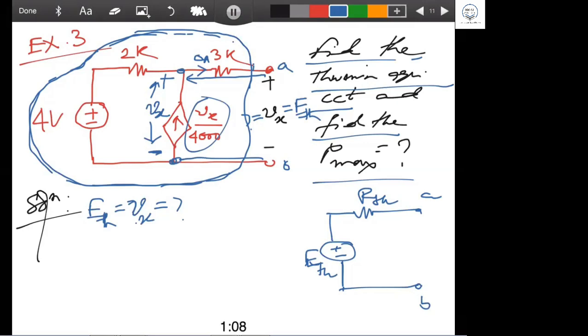Now, the current source current is flowing through this, and this current will go which direction? To the right or to the left? Can you see the current I am drawing here? This current will go from the source, and which way will it go? To the right or to the left? Or will it divide into two? To the left. Because the right side is 0 ampere, because it is open circuit, right? Open circuit means no current flow. So all the current is going through this. This is the current path it follows.